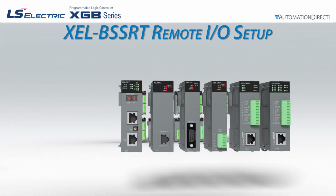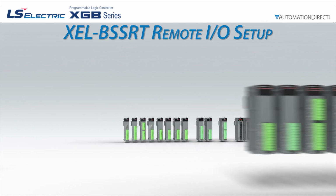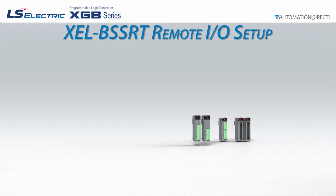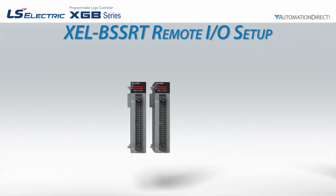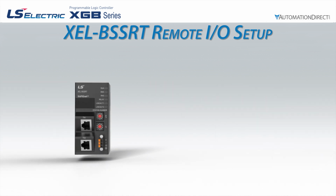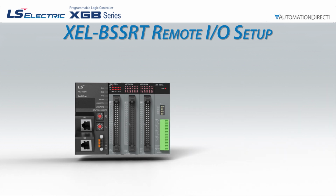The communication and EtherCAT motion modules are not supported. However, the platform does support a vast array of discrete, analog, temperature, and load cell input and output modules, as well as multi-channel high-speed counter modules for encoders and speed detection systems. In our example, we are going to have an XBF HD02A high-speed counter module, an XBE DC32A discrete input module, an XBE TN32A discrete output module, an XBF AD04A analog input module, and an XBF LD02S load cell input module.